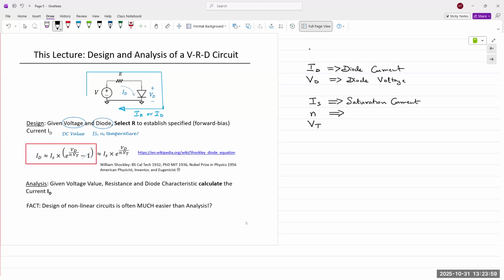They are known as the majority charge carriers, and a very few number of holes. Those are known as minority charge carriers. In a P-type material, you have an excess of holes, meaning more positive charges and fewer electrons, so less negative charges. So they are minority carriers. When we bring P and N-type materials together, there's a junction interface. It gets depleted of all charges. There are only minority carriers present on both sides.